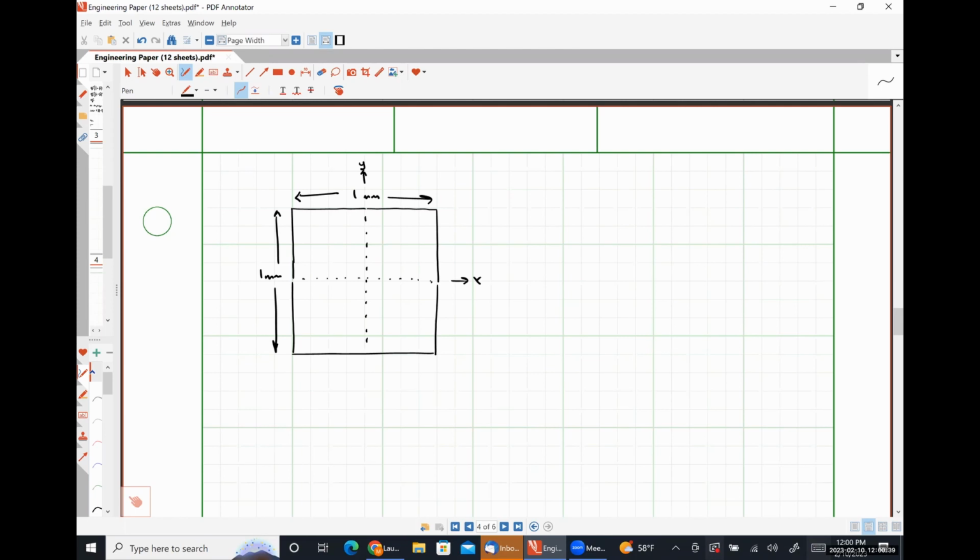Exactly right. The locations of maximum stress, because maximum stress is going to give us our largest change in resistance. I know it's been a while since we've looked at piezoresistive things, so the fractional change in resistance is the longitudinal piezoresistive coefficient times the longitudinal stress plus the transverse piezoresistive coefficient times transverse stress. So to see the largest possible change in resistance, we want our stress to be as large as possible.